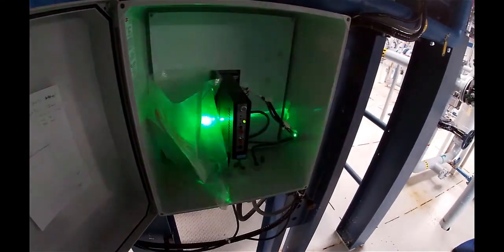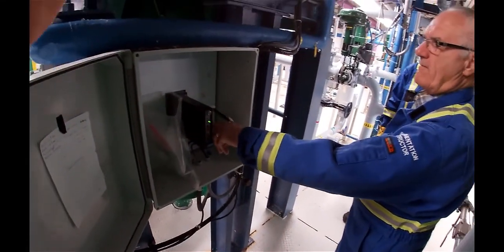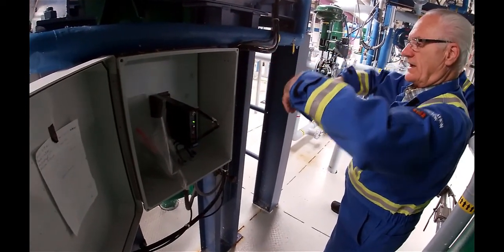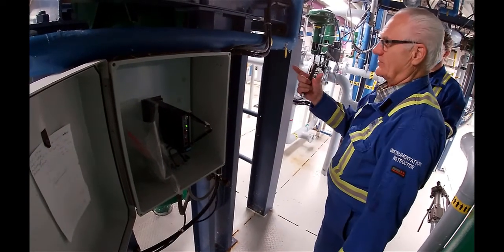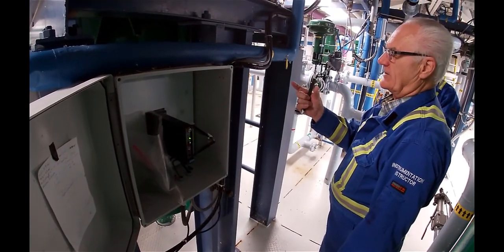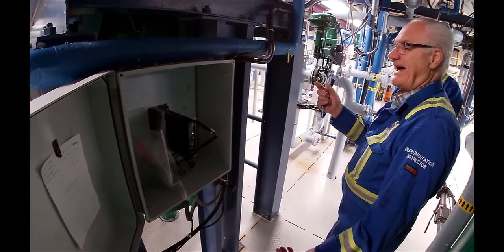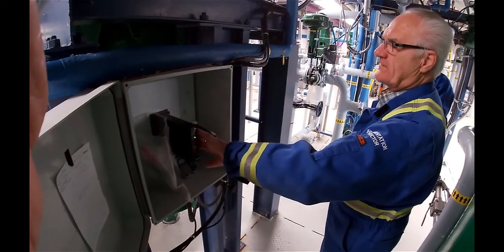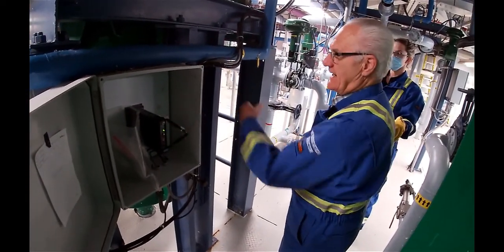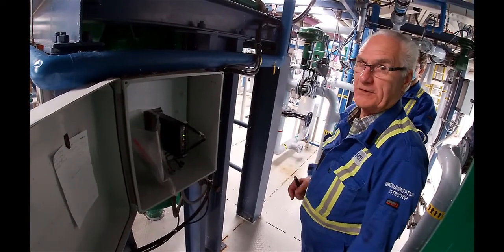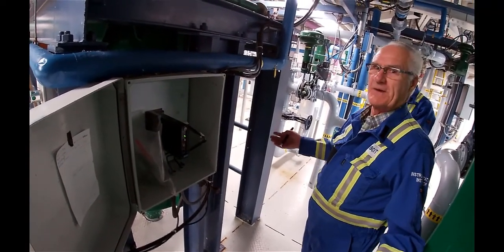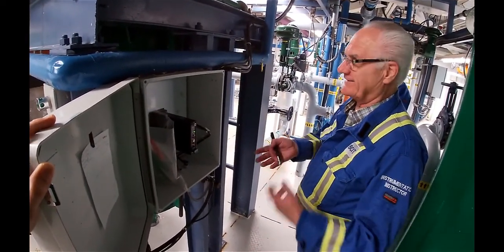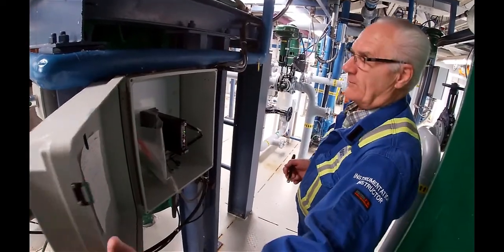So here we have a level transmitter, which is measuring that load cell, and as the weight increases, the load on the load cell, the actual steel cylinder that's sitting in there, tends to compress maybe a half a thou, and we've got strain gauges inside that load cell, and so therefore it measures the weight of the tank, and from that we infer how much water we put in. One gallon of water is 8.3 pounds, and we're putting in 170 of them, so multiply it, and that's the change in weight. Okay, we're done with that.